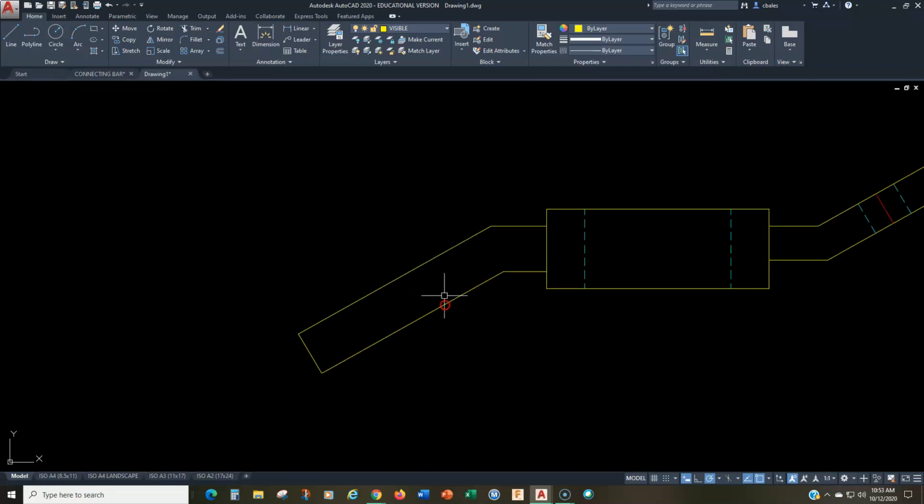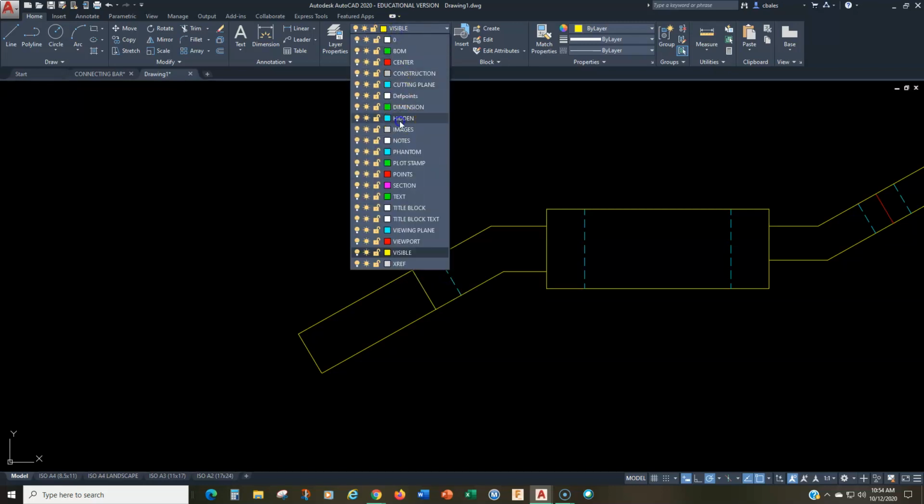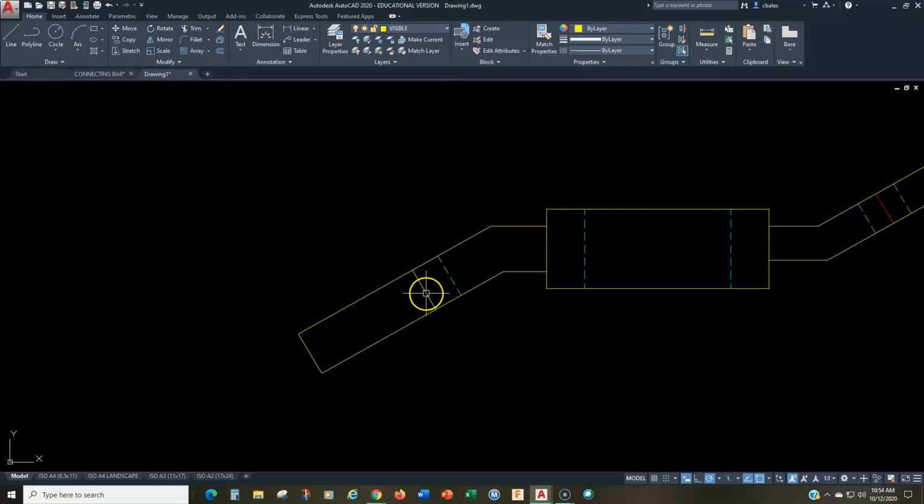And then finally over here we have the slot, which is 45 degrees from the front end, so we'll offset again 45. And then this is the center again. So the radius of that, it's a diameter 20 slot. So that means the radius is 10, offset 10. All right. And we'll get that. And we'll get this one.